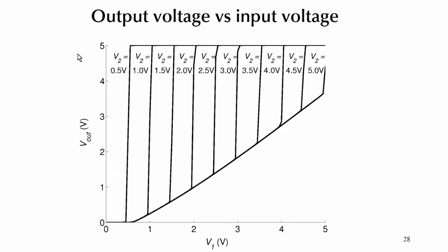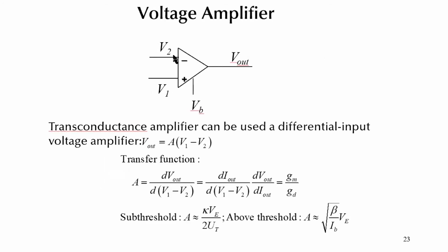Okay, all right, so you guys get the feeling that even with a 5 transistor transconductance amplifier, and you can have the equivalent symbol with the plus and the minus and the output, you shouldn't assume that it operates exactly like the symbol, right? Because this is kind of an ideal picture where you want the output to change as a function of the difference between the two inputs, right? Depending on the circuit, you might get this to be true for a certain set of conditions, a range of values for V1 and V2. And it's also understanding where that is, right? If you want to be a designer later on and you want to use the 5 transistor transconductance amplifier, you don't make assumptions that you should follow this equation all the time.